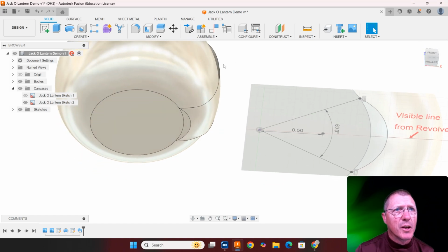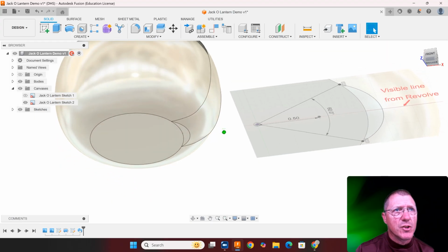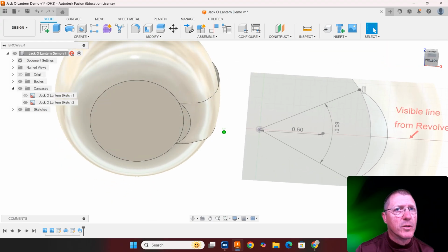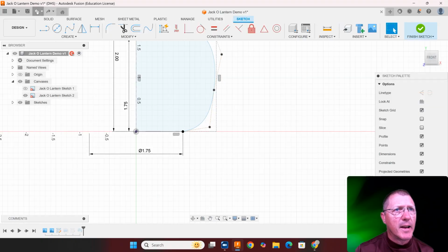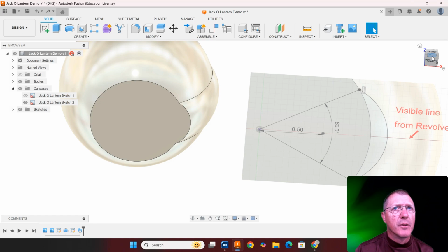And we see the segment also looks kind of wonky. It's under wrapping and so on here. So if you get something like that, you just need to play guess and check with that initial revolve until you get a solid face so that it will shell, because right now it will not. I'm going to just undo that because I had a good segment there.